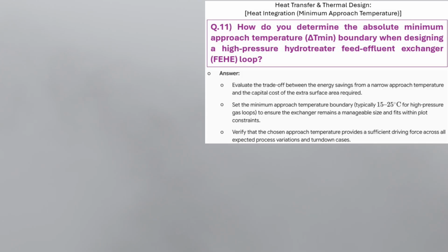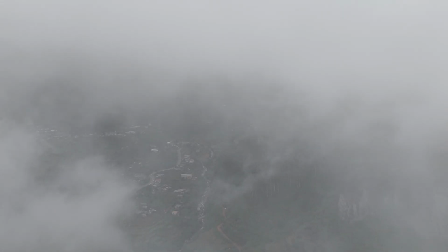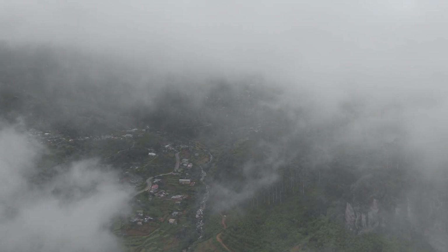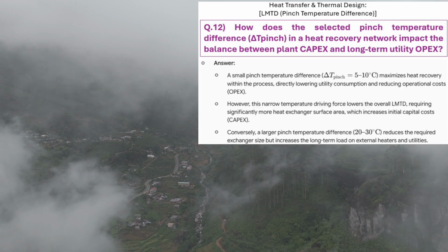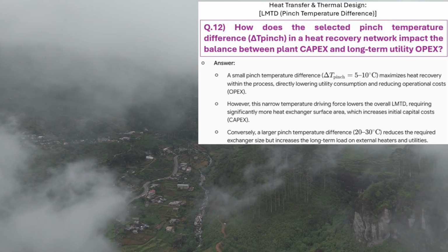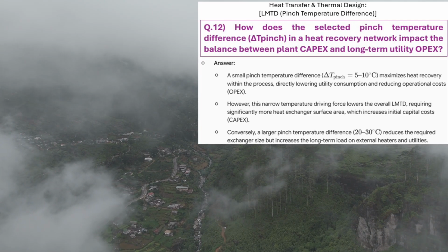If a theoretical engineer forces an 8-degree approach, the mathematically compressed LMTD dictates 10 massive shells in series. 10 shells in series completely busts the plot space. And violates strict gas loop pressure drop budgets, forcing multi-million-dollar compressor upgrades. Furthermore, piping 10 rigidly connected shells in series multiplies mechanical expansion risk exponentially during thermal cycling, practically guaranteeing flanged leak points.